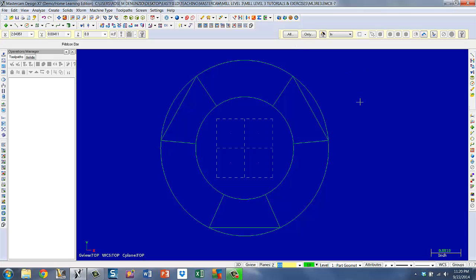Now I can trim some more. Go back to trim. Trim divide, which is right here, works really well on these. Take them out. And now I've got my flats. Check out of that operation. I can eliminate these tangent lines that we were using temporarily because I'm going to build the whole protrusion and rotate it going forward.